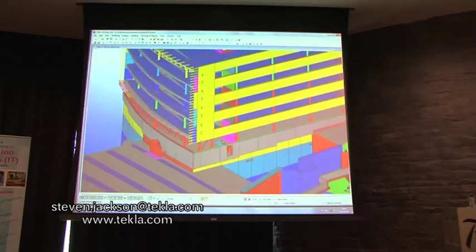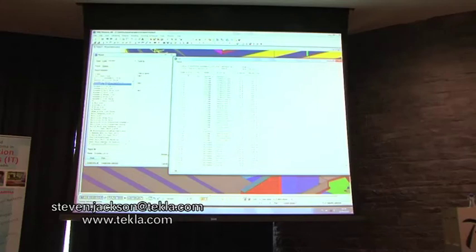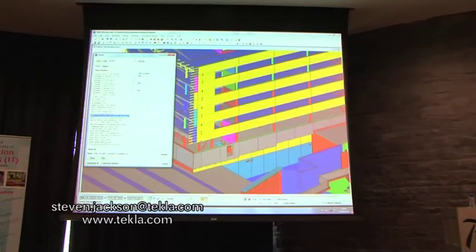So with this information in Tekla Structures, what can we get out? If I go to the reports over here, I go to the assembly list and show this. You see that in this model I've got the assembly position, the name and the profile, areas and weights of all these profiles. You can see the list there of all these units. And of course down the bottom I've got a total of 1,814 steel assemblies in here, and a total area and a total weight.